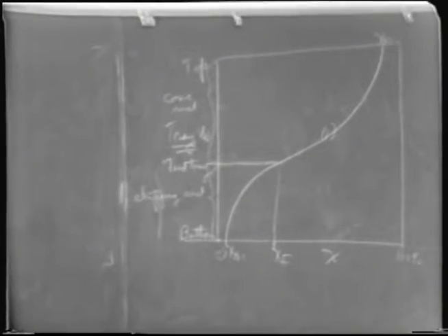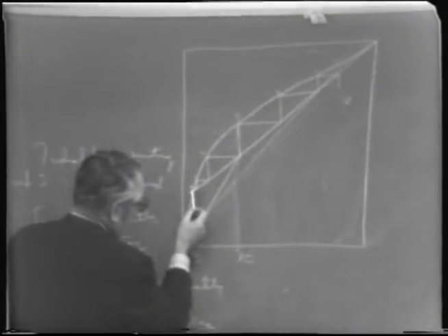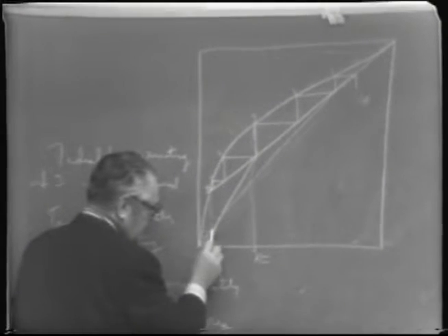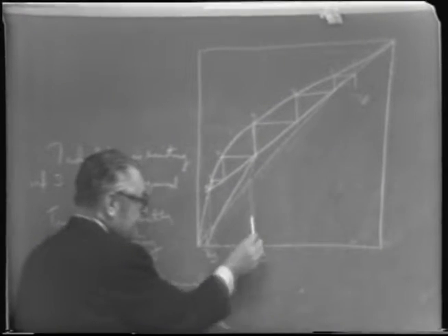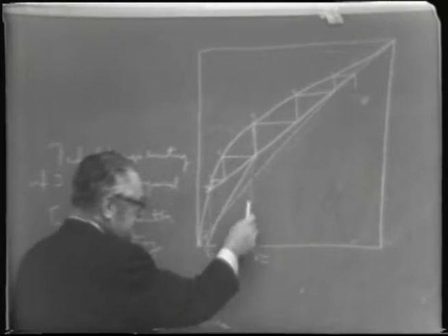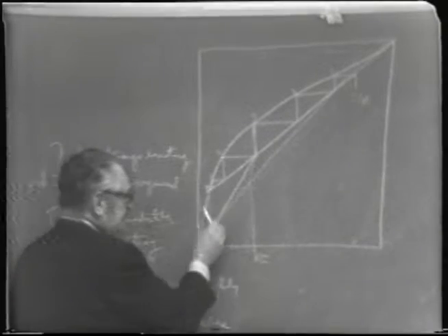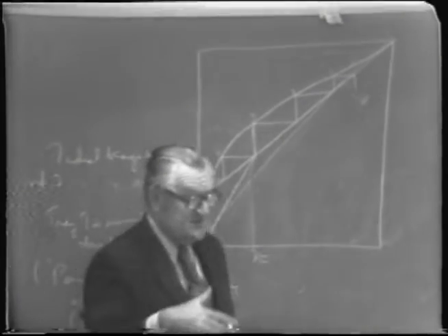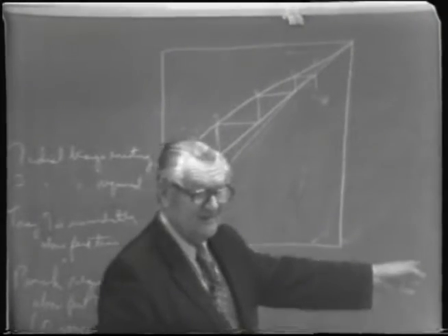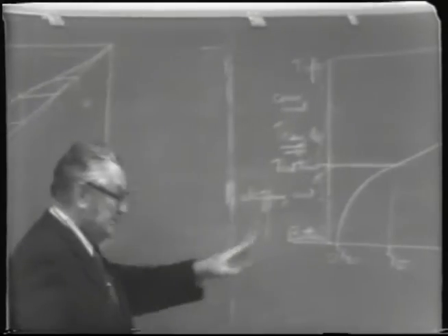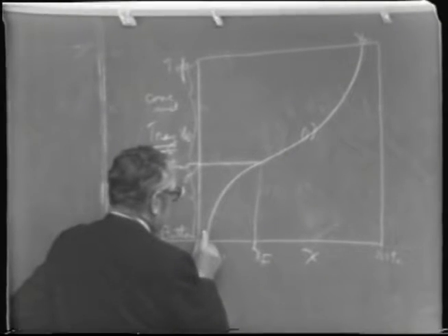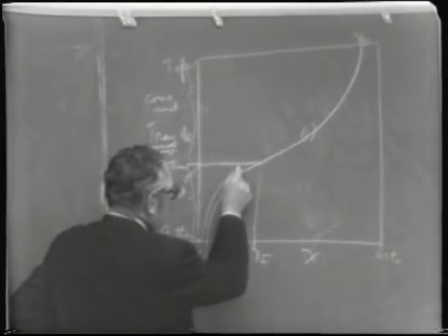And since the overflow from the tray immediately above the feed is considerably lower than it would have been in the ideal situation, it's obvious that a fixed number of steps here is going to lower the bottoms concentration to somewhat lower than it would be under the original design situation.